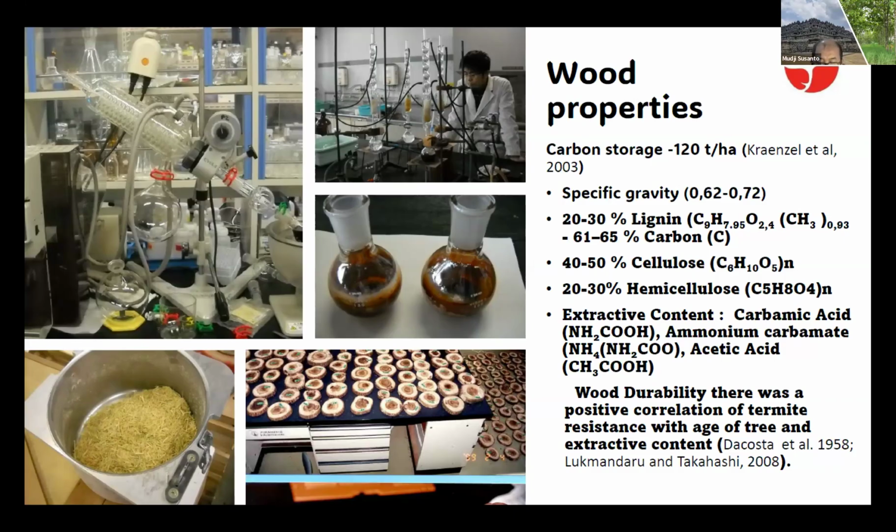Hemicelluloses are crucial for wood quality in woodworking due to their role in cell wall structure and interaction with other wood components like cellulose and lignin. They influence wood mechanical properties, hygroscopicity, and how it interacts with various processes, including adhesion and material development. Hemicelluloses are a major component of the wood cell wall, acting as a bridge between cellulose fibers and influencing their orientation. They affect wood tensile strength, toughness, and resistance to deformation.